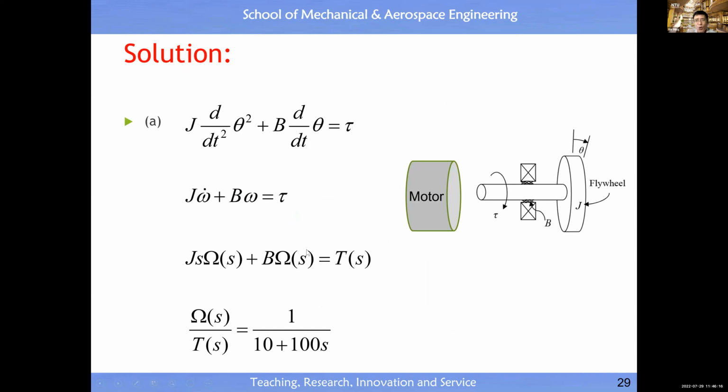So I will go through this to help you understand how to analyze a system under control in control theory. I guess this equation should be straightforward to you. This is the application of Newton's second law. We have the applied torque, which overcomes the viscous friction. Viscous friction is proportional to velocity. Then the remaining energy will contribute to the acceleration of this mass. Since this is a rotary motion, we talk about angular acceleration. Then this is the moment of inertia of the mass. It's quite straightforward. Then this is angular velocity; we use omega dot. Omega is angular velocity. Then we have this equation.